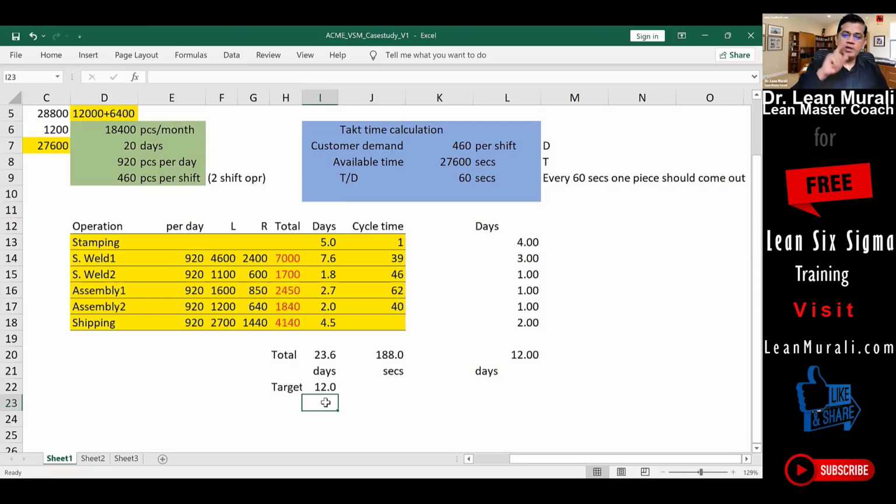One is, if you reduce inventory, the flow will enhance. You can produce in shorter lead times. That thinking process should be clear. The second is, is it possible to drastically reduce inventory? Not always. But is it possible to reduce inventory to some extent? It is possible. But while doing that, some other constraint will come up. You will have to overcome that constraint. The constraint might be something like distances, the setup time, or the machine efficiencies, etc.